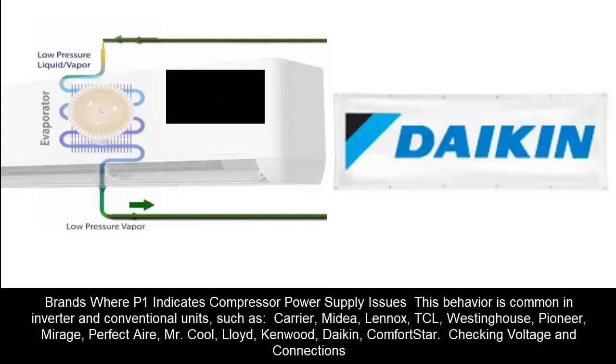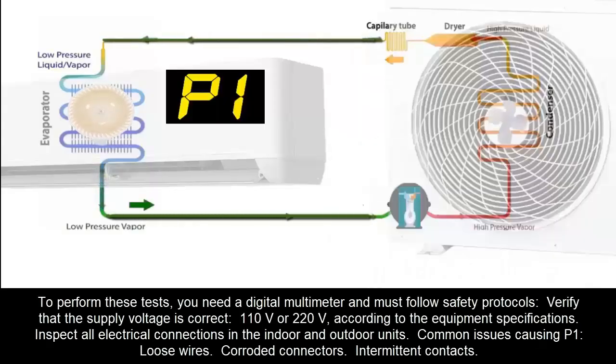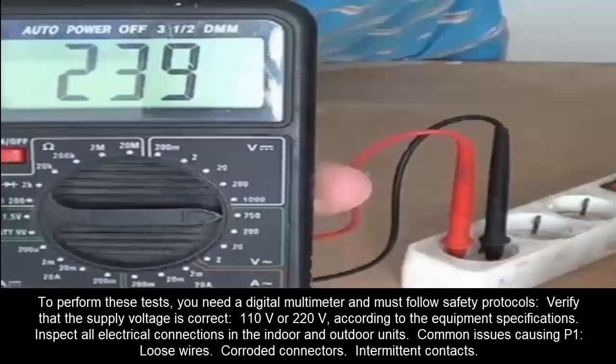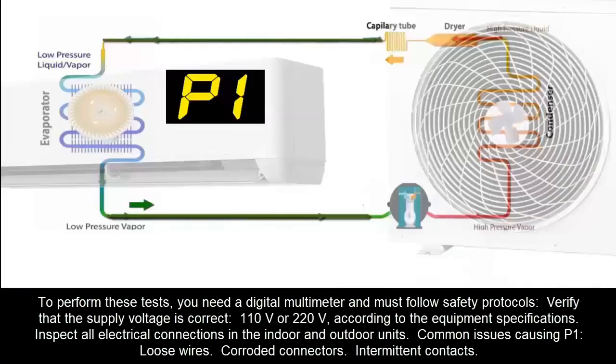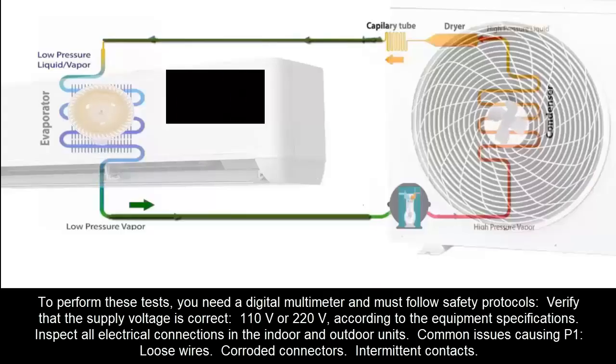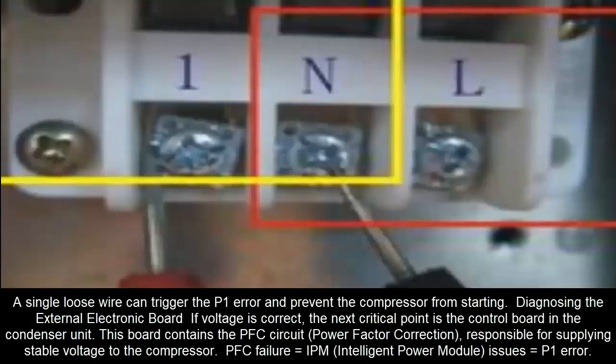Checking voltage and connections. To perform these tests, you need a digital multimeter and must follow safety protocols. Verify that the supply voltage is correct, 110 volts or 220 volts according to the equipment specifications. Inspect all electrical connections in the indoor and outdoor units. Common issues causing P1: loose wires, corroded connectors, intermittent contacts. A single loose wire can trigger the P1 error and prevent the compressor from starting.